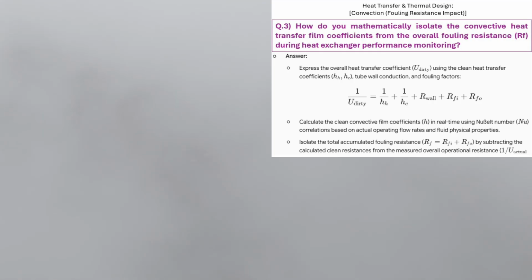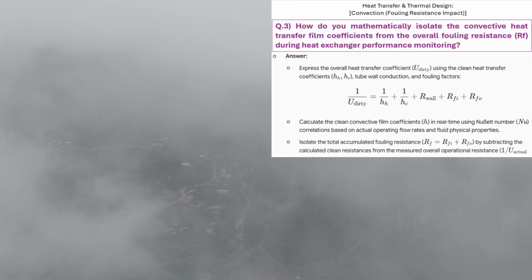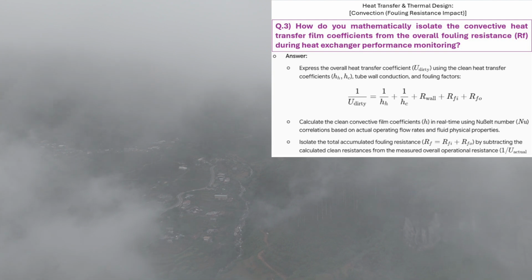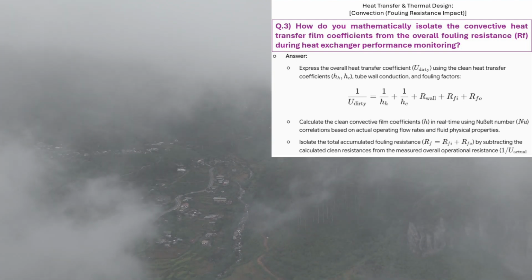So you separate the hydraulic flow profile from the physical buildup. Quantify that. Give me an operational scenario where failing to make this distinction led to a costly error. A classic high-cost example involves a shell-and-tube crude preheat train. The DCS suddenly registers a 20% drop in heat duty across a critical preheater. And the shift team assumes the bundle is coked up. Exactly. They assume a bad batch of crude caused severe coking.